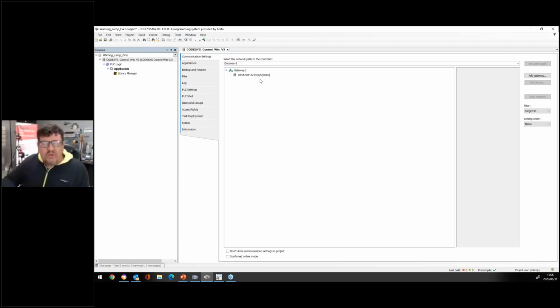Now, because I'm using the internal PLC, the soft PLC, not an actual hardware PLC, I need to have a name for that PLC. Now, my name for it is my desktop. I'm clicking right here, and I go over to the other side and say set active path. Guys, the moment when this changes into a bold color, then I know it will be connected to my PLC. That means it's connected now currently to my CPU, to my device.